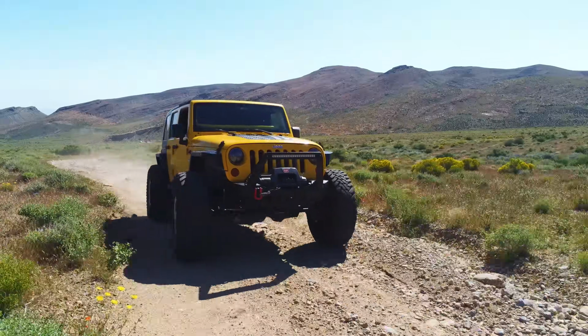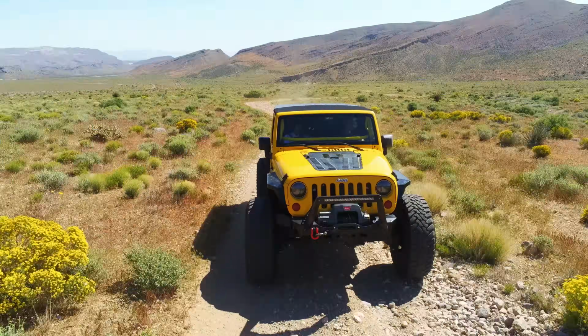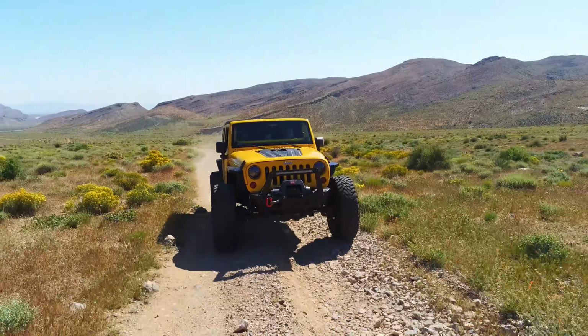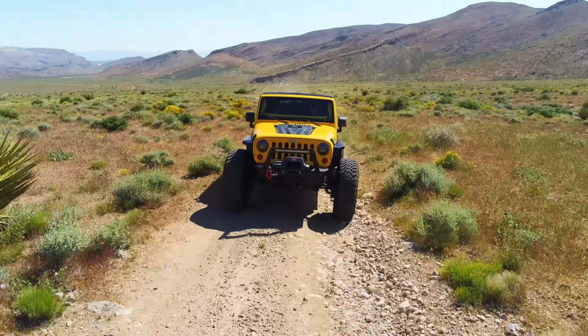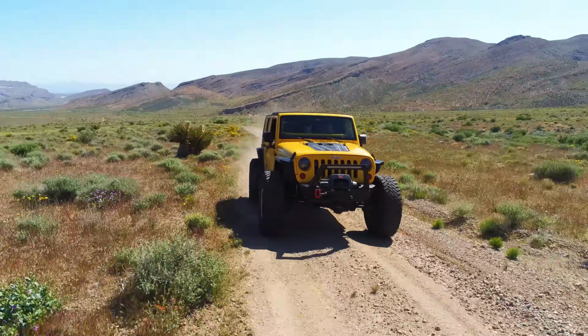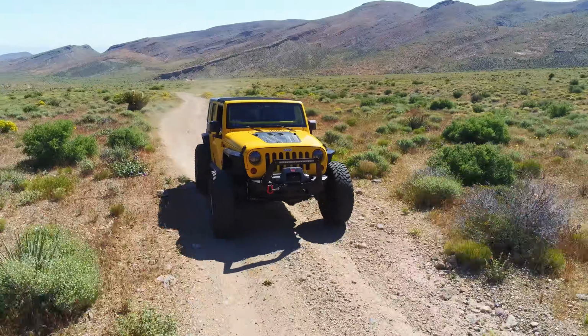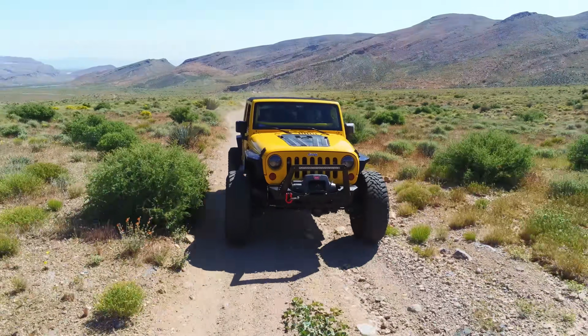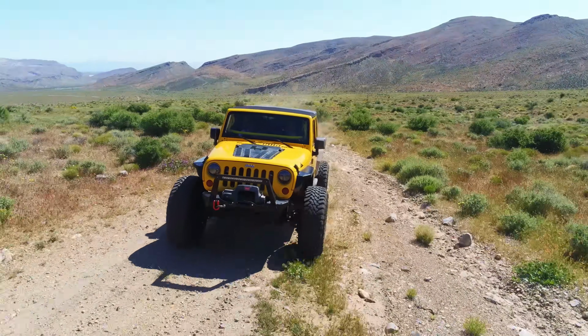The operating system will switch out of closed loop. It won't look at the O2s for fuel control. It will check the O2s periodically, but basically those O2s are going to flatline lean because we're going to be running 16, 17, 18 to 1 air-fuel ratio. This was really popular back in the 80s and the early 90s with the lean burn engines.